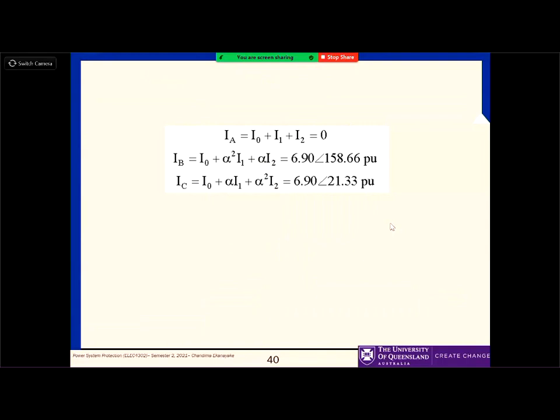Yeah, see, like that. And then you can see that IB and IC are 180 degrees out of phase, because the fault is in between. And then not always, because if it is going into the ground, sometimes it's not, right? Two currents connected and then going into the ground, then it's slightly different. If it is a line to line fault, then they are equal, right?